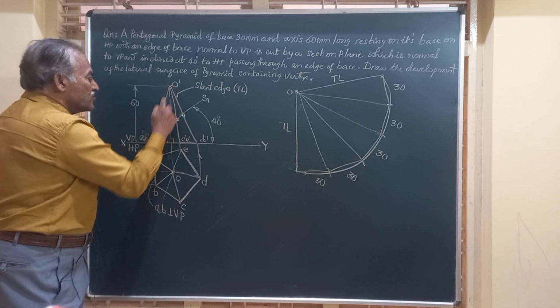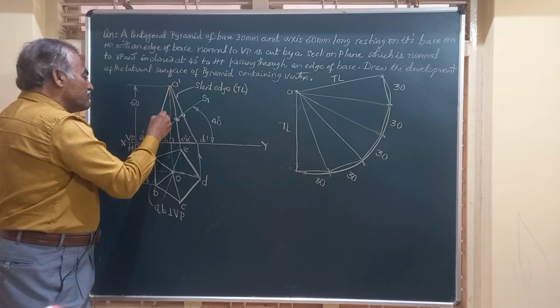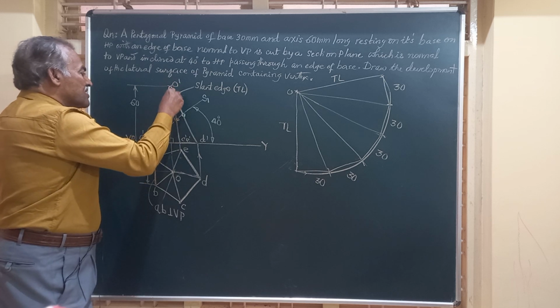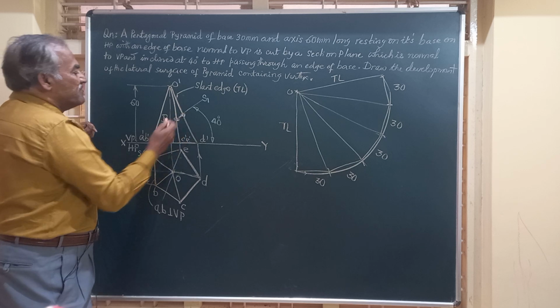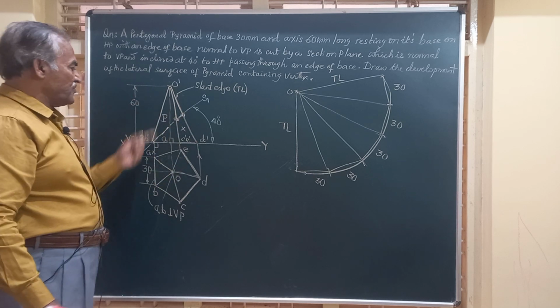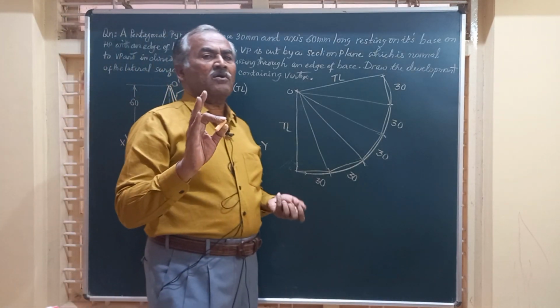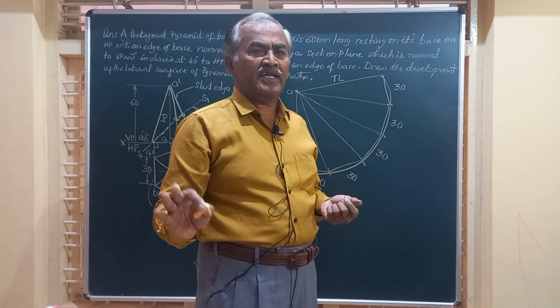So friends, this portion I am going to retain, and hence I will show this by dark lines. So these are the dark lines you have got, and this is the section. So we want the development for the upper half. The lower half is thrown out. And if you observe the front view, friends, here none of these five slant edges have been removed totally.